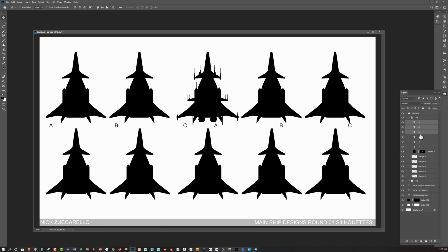So I don't need this last one, but I'll drag this out like right here. I don't need this. See? Let's tap T to go into there. Control Enter will finish this. And I'll do E, Control Enter to finish that.